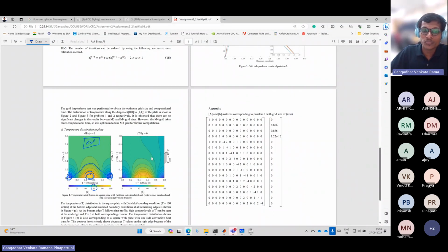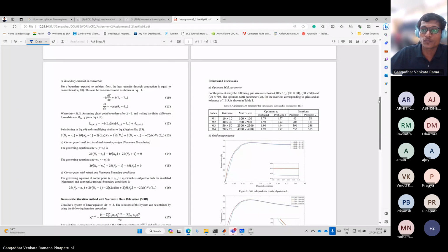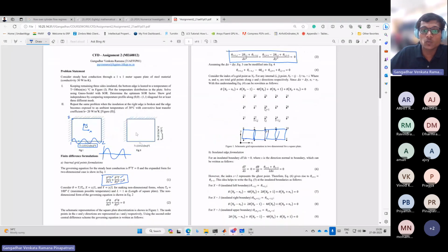And one more problem, which you solve the same way, but additionally at one end, you remove the insulation and add a heat convection. A convection due to the air. Air is passing by, touching this metal plate's side surface. If it is passing at some particular velocity, with some non-dimensional heat convection coefficient, that means it is taking heat. Just assume that it is taking heat.